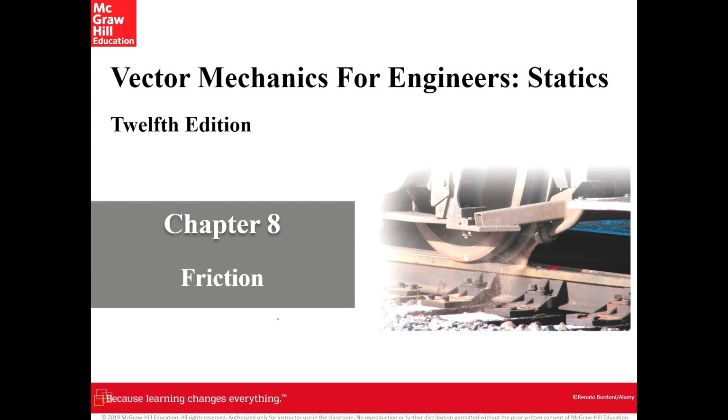And once you move through your studies and you learn about thermodynamics, you'll see that friction also contributes to something called heat. So if something has a lot of friction, usually it gets pretty hot, and you have to design systems to cool down, like the pistons in an engine, you have the oil. But heat usually translates to losses, so energy losses. So your system gets less efficient by gaining heat, and the more friction you have, the less efficient your system is. But again, sometimes you want to have high friction because that's really the goal of the system, to be able to avoid slip. So regardless of what your design is, you have to consider friction either to minimize or maximize.